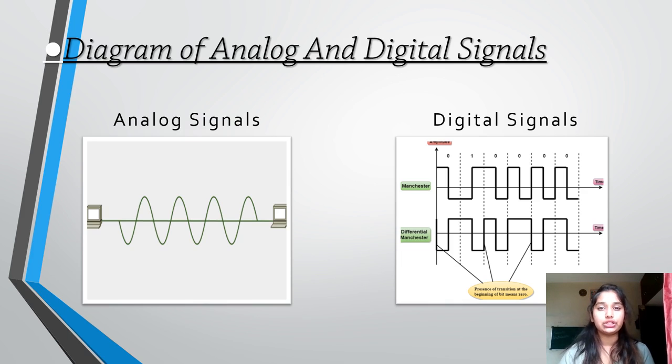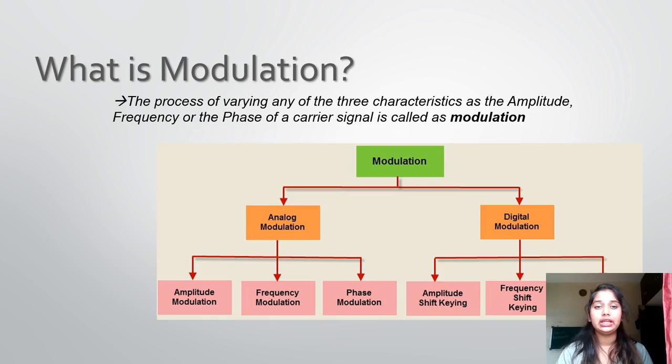Let's see what modulation is. Modulation is the process of encoding information from the message source in a way suitable for transmission. Need for modulation in a communication system: the message signals have a very low frequency, due to which they cannot be transmitted over a long distance. Hence, such low-frequency message signals are modulated over a high-frequency carrier signal due to the following reasons: practical length of antenna, narrow banding of the signal, frequency multiplexing, and effective power radiated by the antenna.